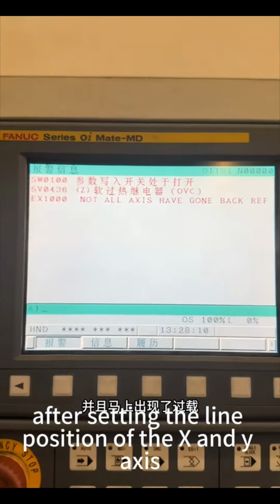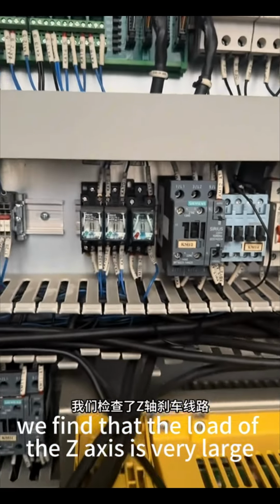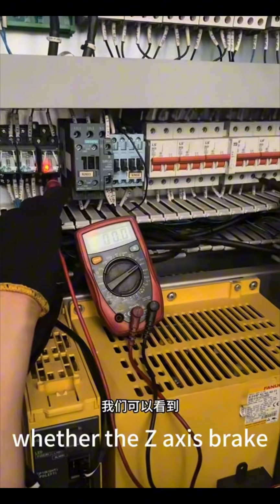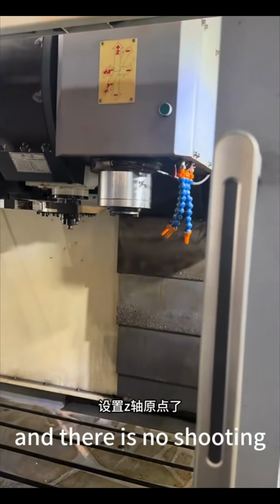After setting the limit position of the X and Y axis, we can start to adjust the Z axis. When we move the Z axis in manual mode, we find that the load of the Z axis is very large, and there is an overload warning immediately. In this case, the first thing we consider is whether the Z axis brake is open correctly. So we checked the Z axis brake line. The investigation took a relatively long time, and there was no footage.